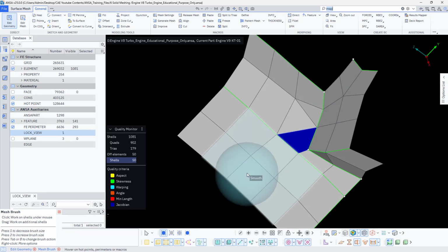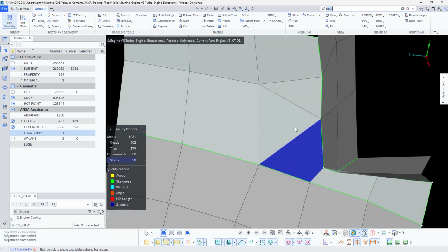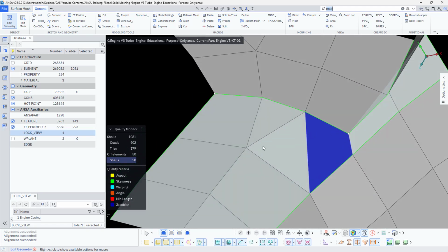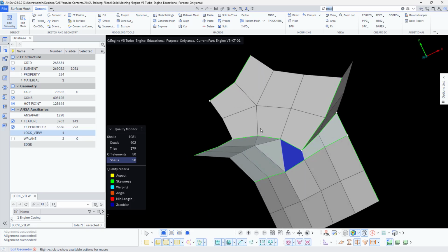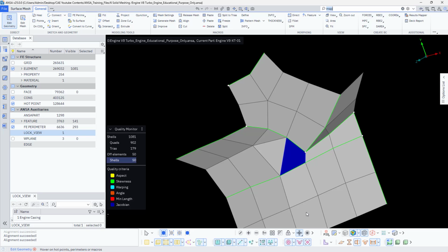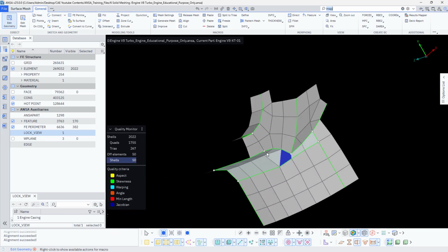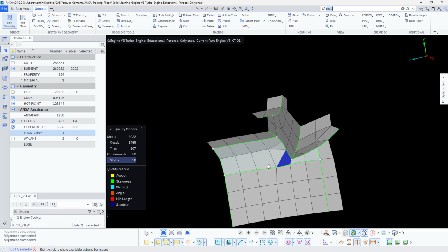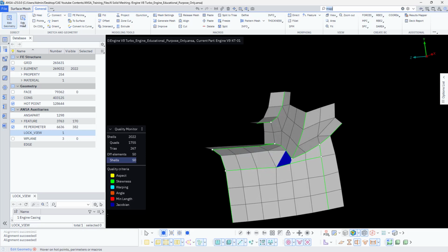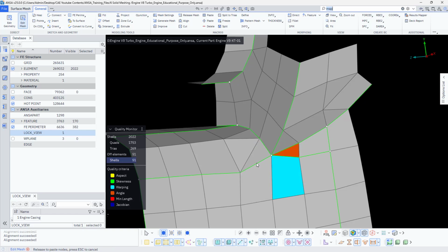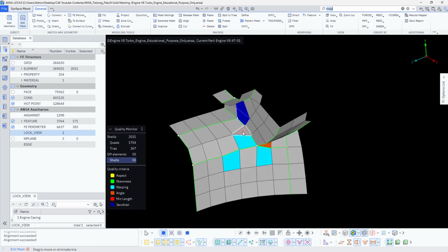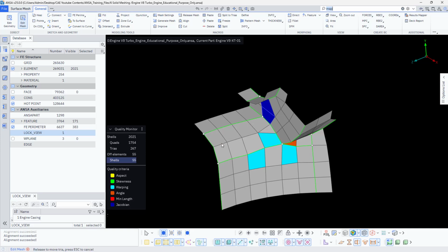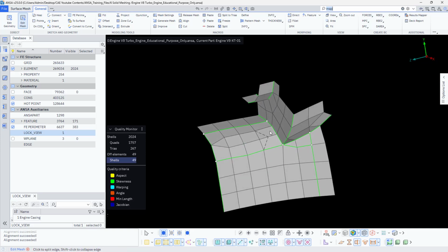Brush is not working for this region, so let's try to find the manual solution for this. In this case, you can just take one more layer to see what exactly it is. So this region, I would like to do like this. I'll join these two, and here like this, and remove this one. And here I would recommend to have this one 3 rows. So you can just drag this one up to here somewhat. So this will be fixed. Okay.